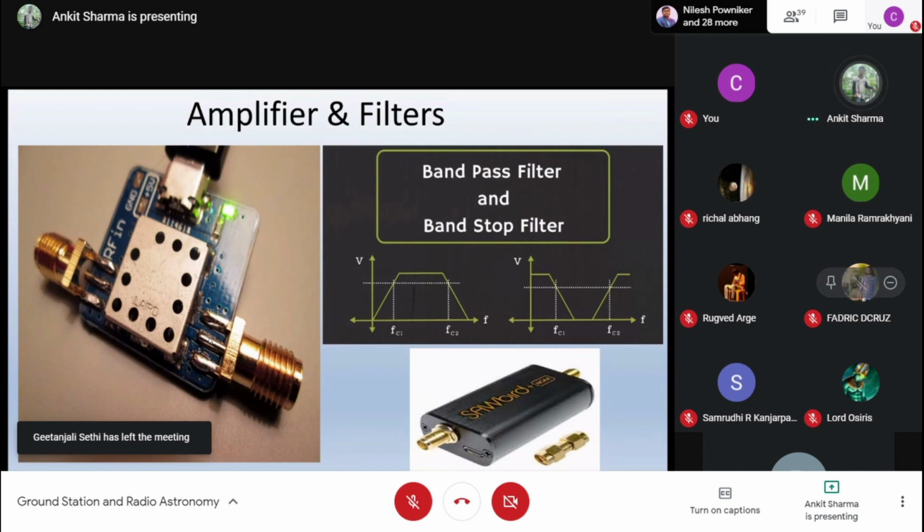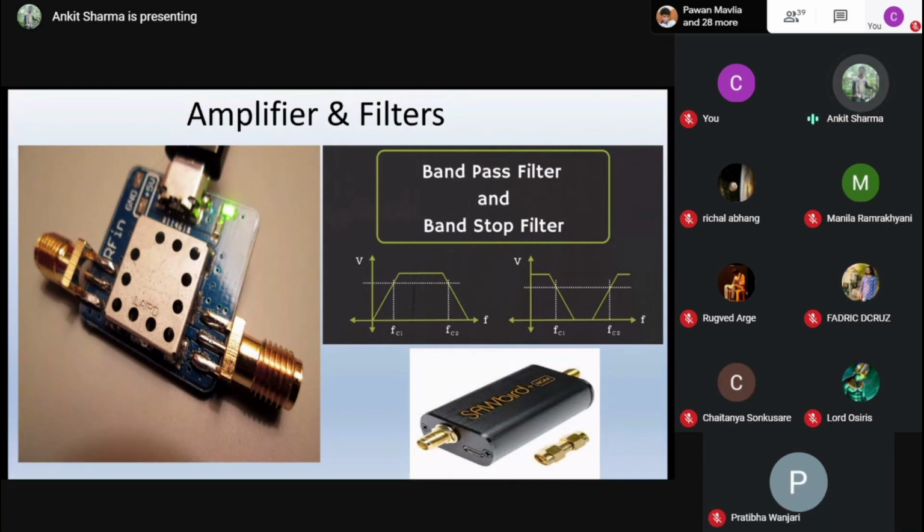But yeah, if you are at a place where you have high interference of the surrounding signals, it depends upon where you are and what the noise around you is. You have to do your noise calculations. If your noise bed is higher than the signals, then you won't receive the signals. So you will need amplifiers and filters to filter that particular thing.